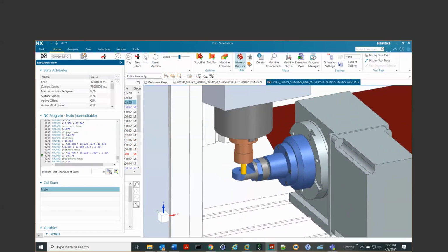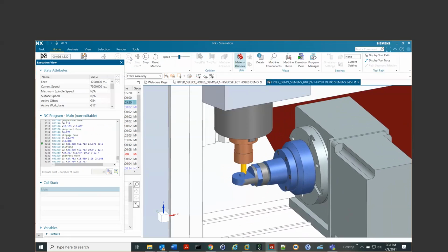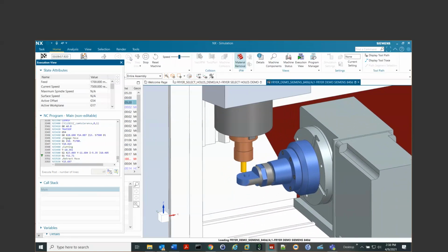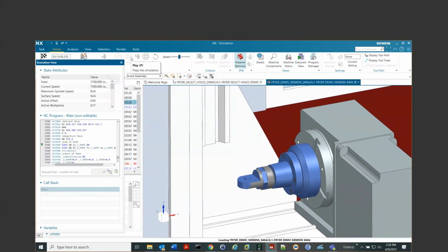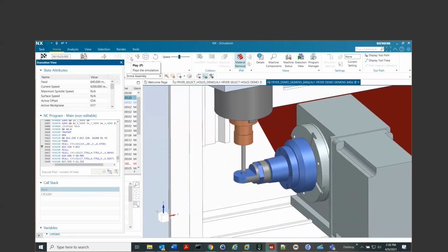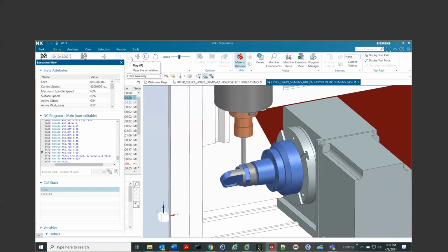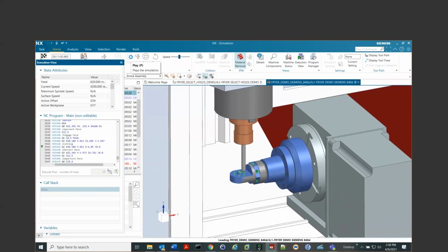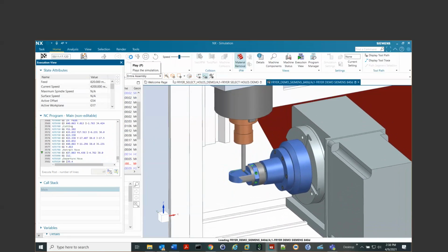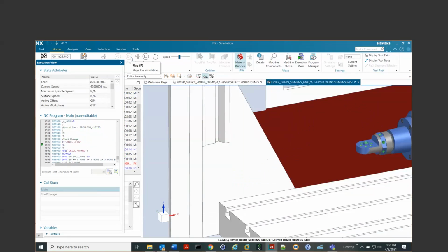Here we're going to do the same operation type where we're going to take a cleanup pass, 5% of the step over the tool. Spot drilling all the holes with the correct diameter. Once again, the geometry is indexing the part, not construction geometry. Milling the chamfer with the same tool saved me a little tool change time.